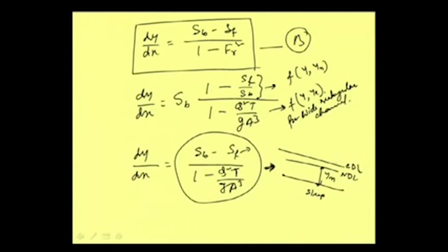But in gradually varied flow, we are putting some obstruction here. Though the slope is steep, water may be rising like that, and so it is going to this level. That is, the depth of flow at any point may be more than our critical depth, though the slope is steep. So, based on all those conditions, if a flow is occurring above critical depth on a steep slope, the name will be different. In a very systematic way, we classify the gradually varied flow considering all these different concepts, and then we name them, and after that we will go for computation of gradually varied flow.